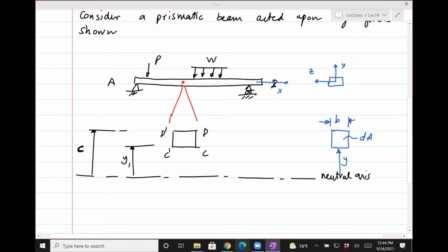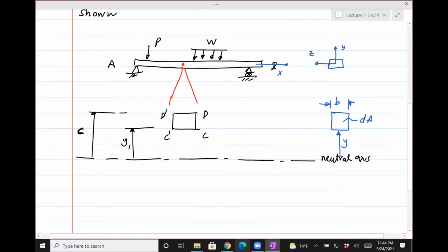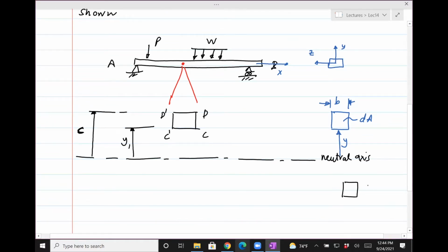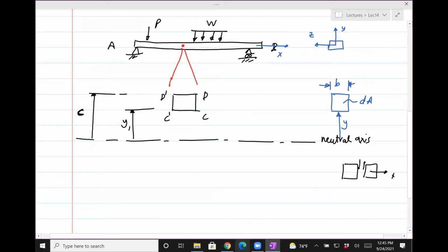So first of all, what a shear force does is it basically causes one plane to slide against the other. Now, that shear stress cannot exist by itself. There's a complementary stress which is produced at the other surface. What I mean by that is, if there's a beam like so, there's a shear stress along the X. This shear stress on this face will produce a shear stress below, which will be complementary. That's what we derived in the previous few sections back. The shear stress is complementary.